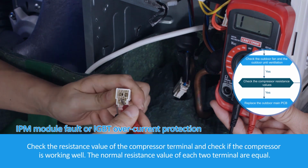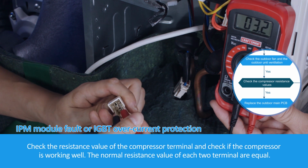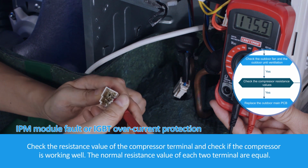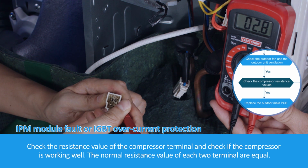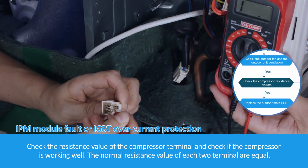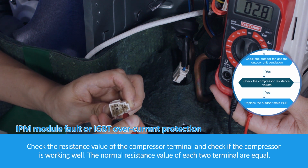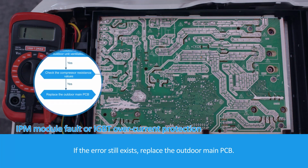The normal resistance value of each two terminals is equal. If the resistances are not equal, replace the compressor or the whole outdoor unit. If the error still exists, replace the outdoor main PCB.